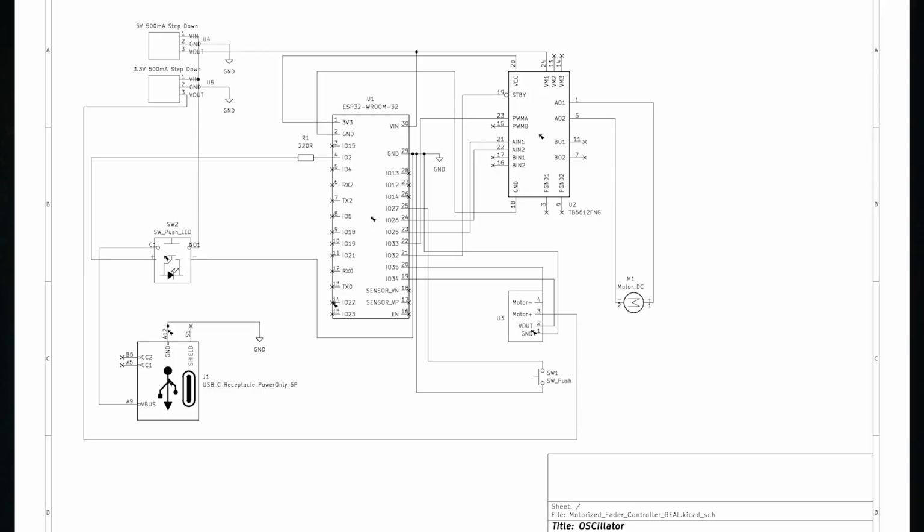I think I'll want to make a PCB if we continue to make improvements on it. But going forward, the main things that I want to change are figuring out a better battery solution, either a better way to mount external batteries or build in an internal battery. I definitely want to add an external antenna because the ESP32 uses 2.4 gigahertz, which is so saturated, especially on set.